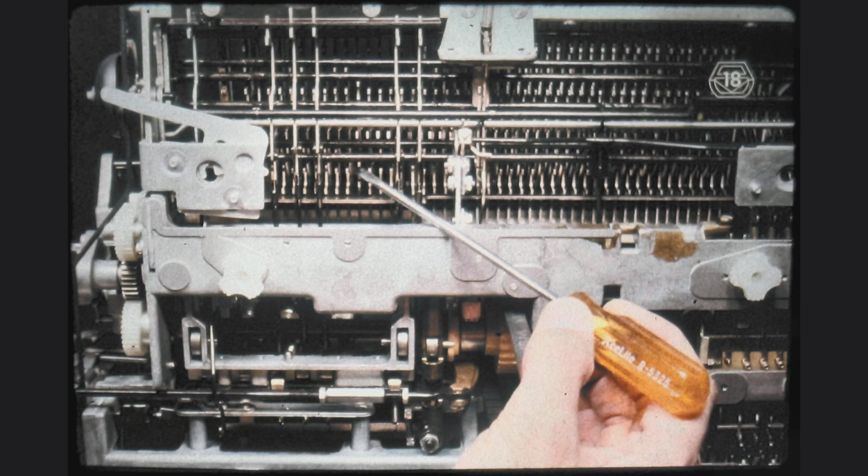What can we do when a character interposer is latched down and we really do not want it down? One option is to simply cycle the typewriter through a print operation, and the interposer will be restored at the end of the operation. We will see in detail how this is done shortly. Another option is illustrated here.